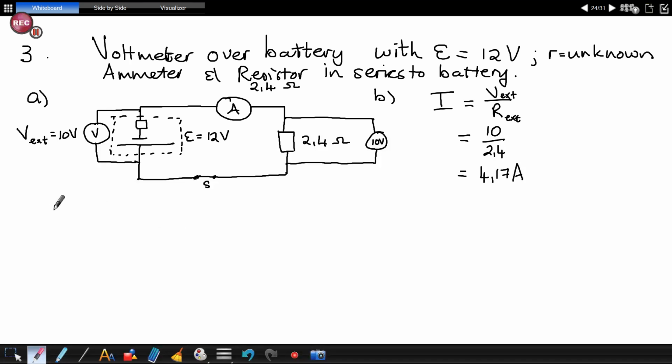Number C. Use the value calculated in B to determine the internal resistance of the battery. How am I going to get internal resistance? The same equation, but you say r equals V over I. Okay, little r equals V over I. Is that what you'll do? Yes, ma'am. But what will your V be then? My V will be the 2. Where do you get the 2?